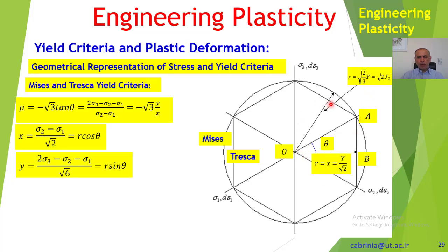And we determined different values in this figure for the yield criteria, Tresca and Mises. Also, we derived this parameter, which we call the load parameter, and we said that if we move 30 degrees here, from 0 to 30 degrees, we could get all the possible states of stress in the yield locus.